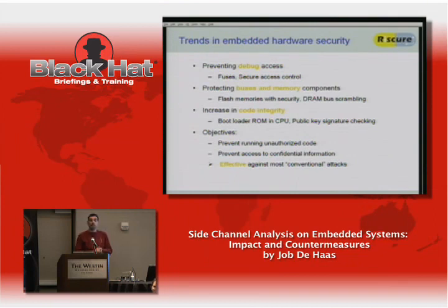And then the last part is actually also quite significant. Protecting the integrity of the code that's allowed to run on the system. So it actually prevents you from writing your own application and running it on the system. And this goes from simple boot checks, where during booting a hash is checked, a signature with public key system is checked, to full runtime integrity checking that can run in sometimes sub-second over the whole memory space, doing SHA-1 hashing, for instance, making it quite difficult to inject changes into your code.